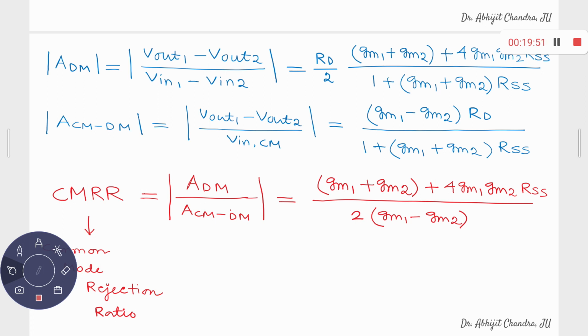In the small signal analysis, we have categorically assumed that the drain resistance was basically one discrete resistance in the form of RD. But we have discussed the common source amplifier, common gate amplifier, common drain amplifier in the last unit, and hopefully you have noticed that typically this resistance can be replaced by some other loads. For example, you can have the current source load, you can have the diode connected load, and each of these loads has its own advantages and disadvantages.